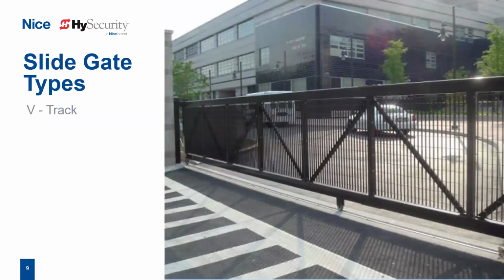And then that will be your cantilever slide gate. The other type is V-track. V-track is somewhere where they're going to have a little more level roadway. They're going to anchor some angle iron to the road and attach wheels to the bottom of the gate, as shown here.